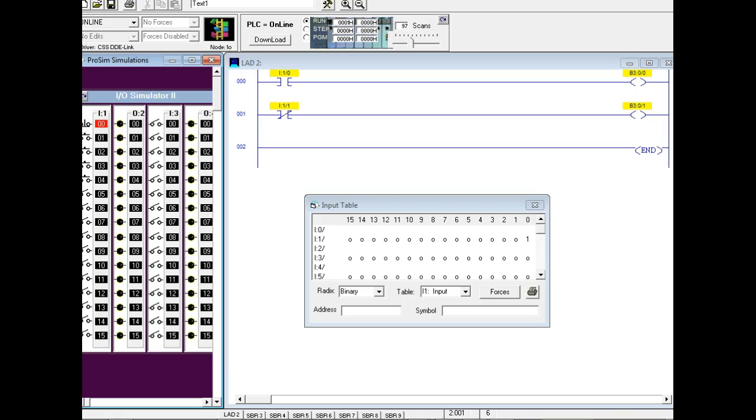It means current is getting through that contact. Okay, do y'all understand? But wait, it's a normally closed contact, and up here it's normally drawn as normally open. And that's what gets electricians confused: how can you have a normally closed contact over here and draw it as a normally open contact in your PLC program?